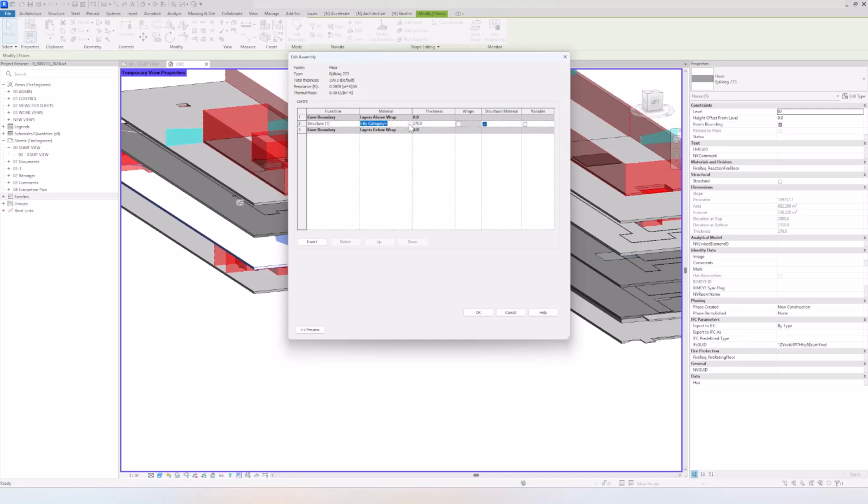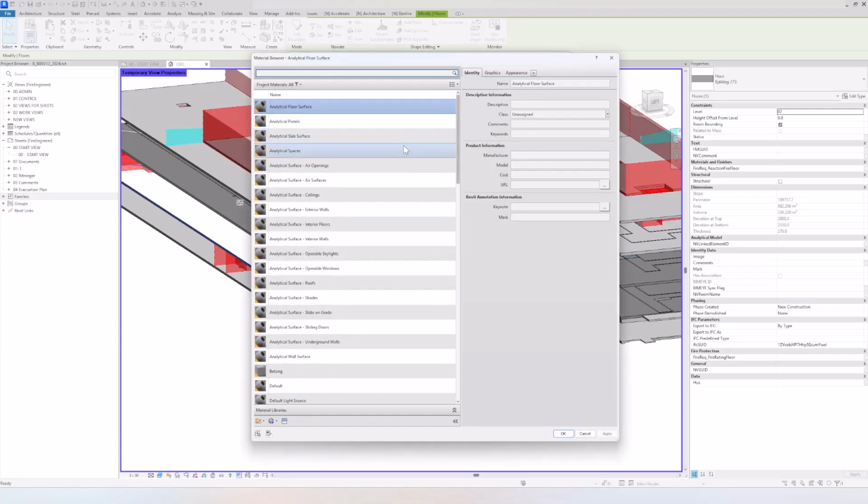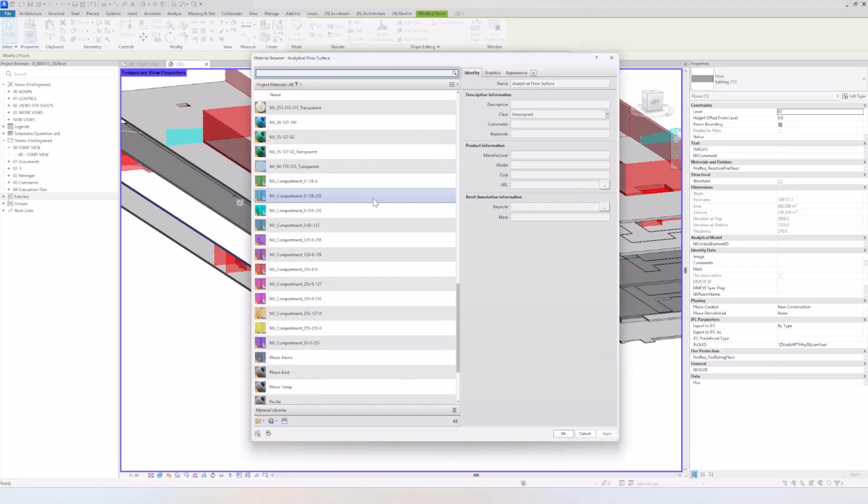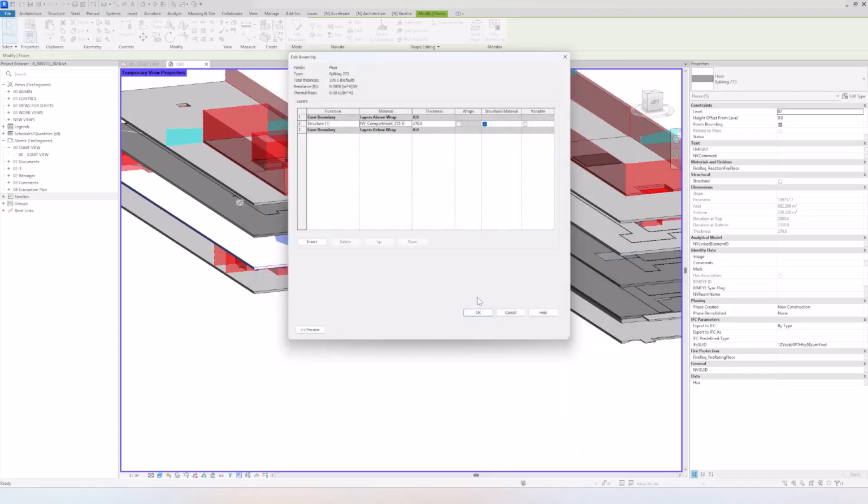And we're going to add a material. So it's going to look quite nice. So I'm going to go here into material, and I said it's going to be red. And I know this one is going to be all those Naviate compartment colors. And we have the different RGB colors here. And this one is red as well. If you're uncertain, check in your template which color would go with the different requirement. I will go OK. And that is my color.